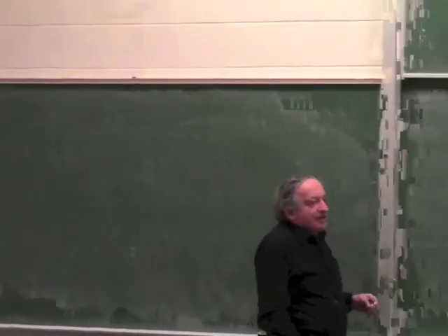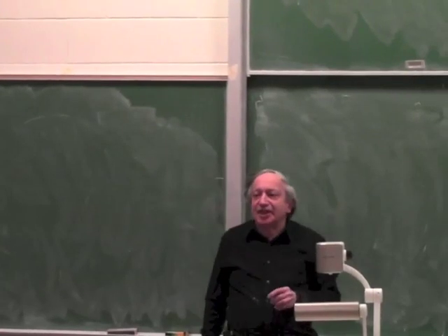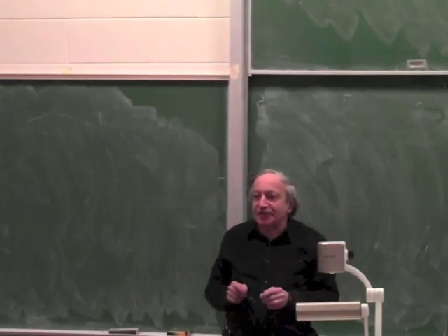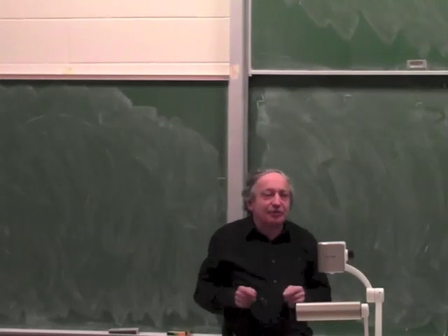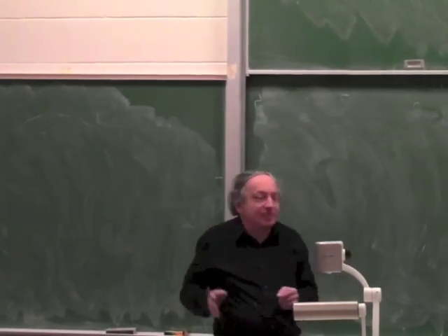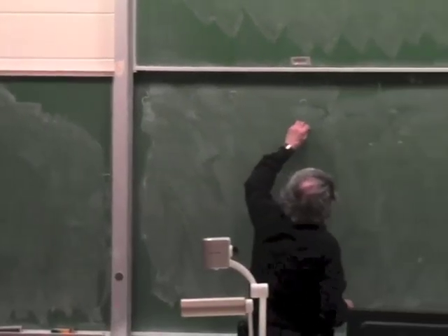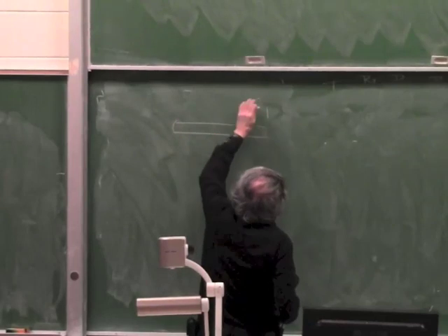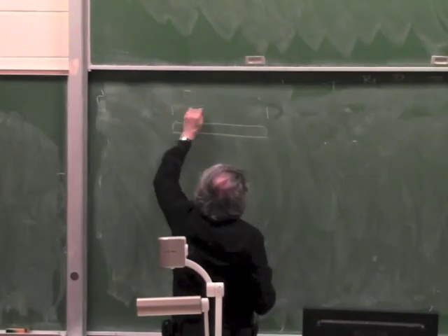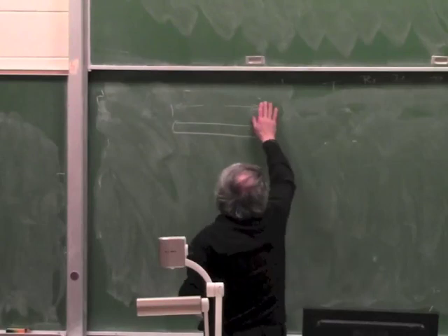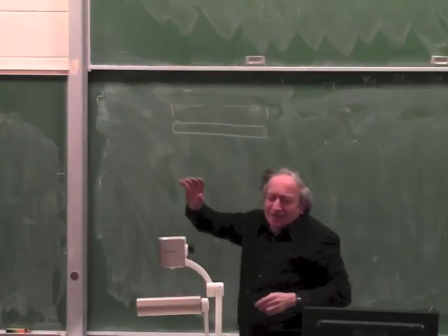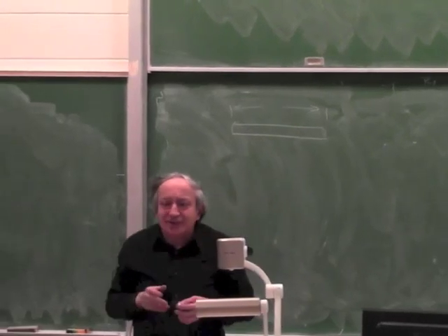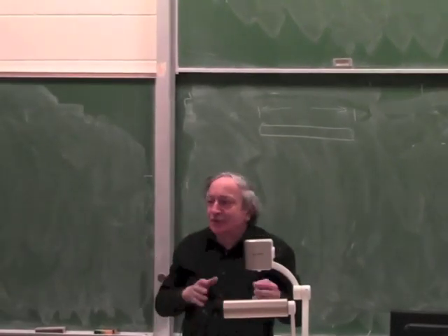So let's go back to actuators which are 100% efficient. In other words, all the copper in the magnetic field produces force, and we want to understand what the theoretical limit is. We have a piece of copper, meaning conductor, it doesn't have to be copper, but in actuators there are really only three materials which make sense for coils: copper, silver, and aluminum.